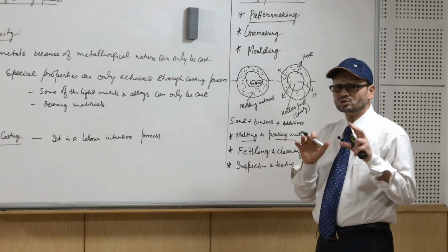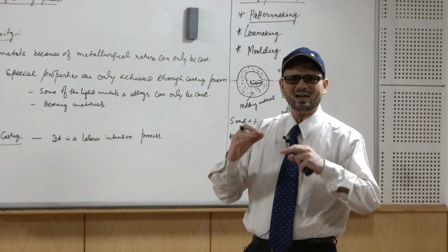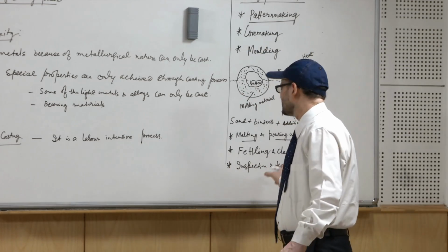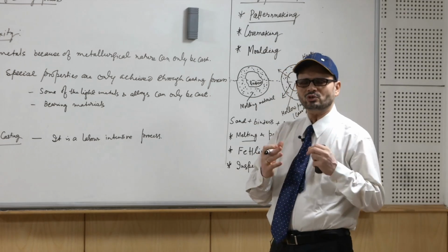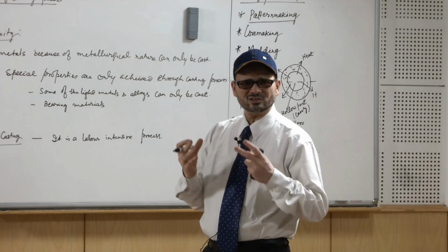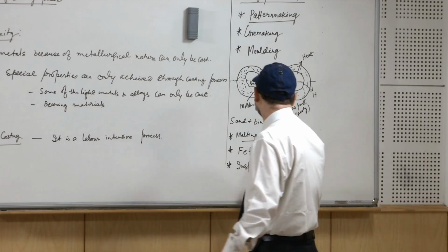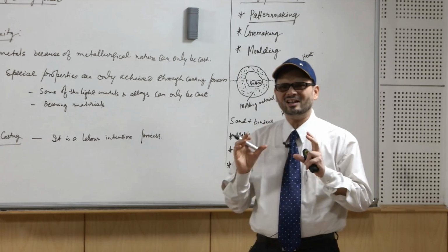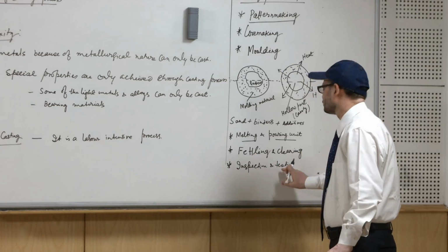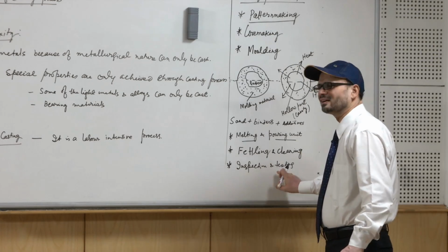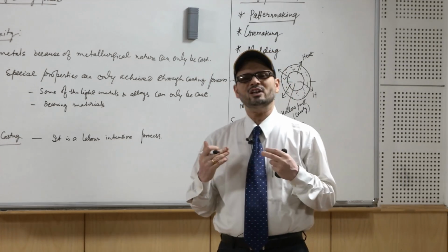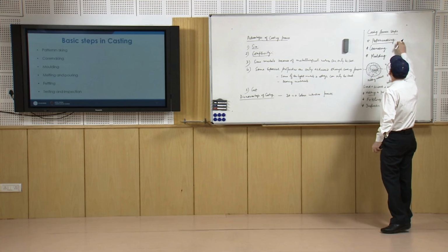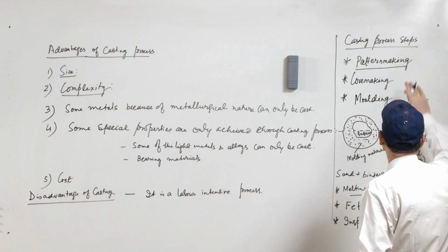So, for that it goes to the quality control section, where you have different types of testing units, like you have magnetic particle testing, you have use of different types of rays. So, all these things are carried out either on all units or on the critical units, and by also sampling you do this inspection and testing, and finally it is sent to the customer. So, these are the normal steps in the casting unit,